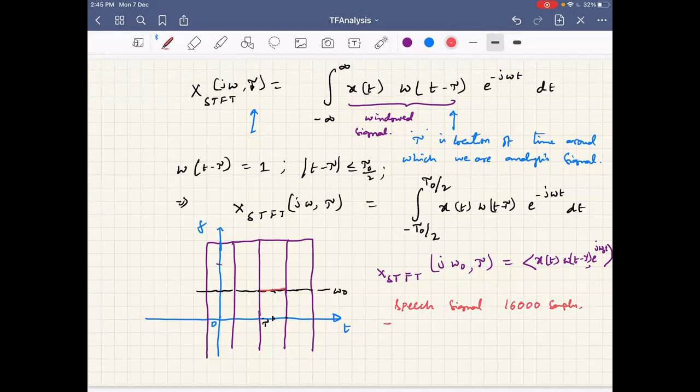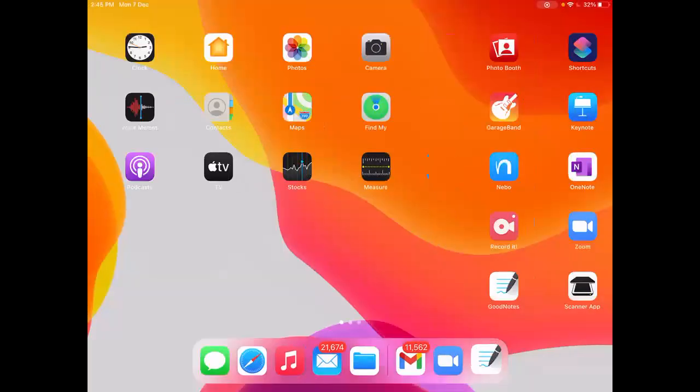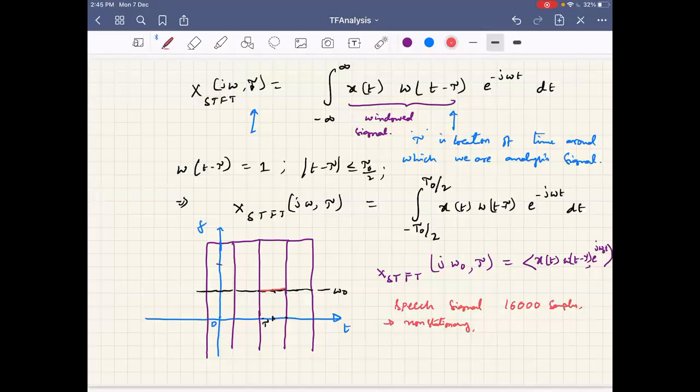This speech signal is non-stationary, and hence it may have several frequencies at different durations, even a mix of frequencies at a given duration. I would like to analyze the frequency content of the signal, and also localize at what time instant these particular frequencies have occurred.